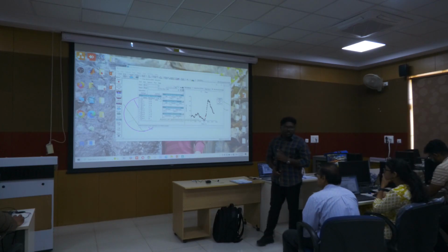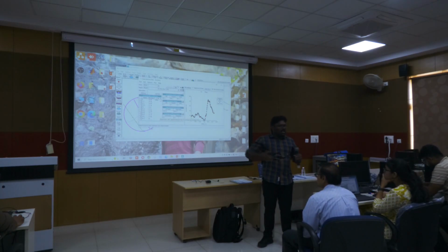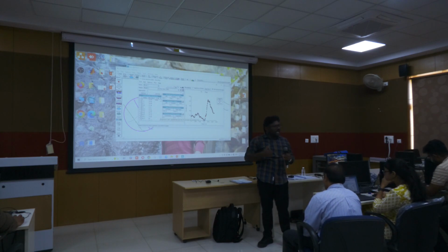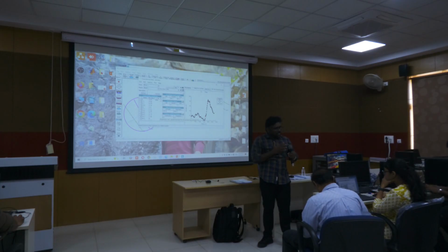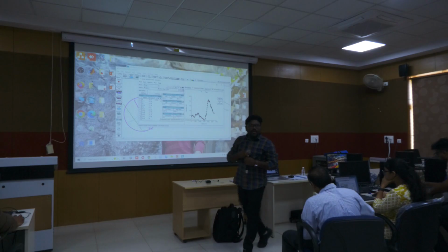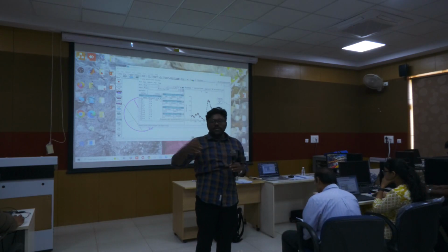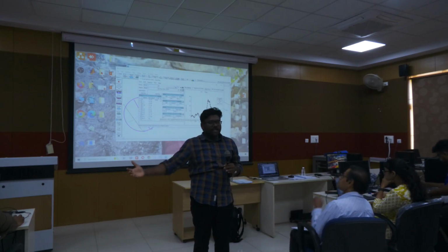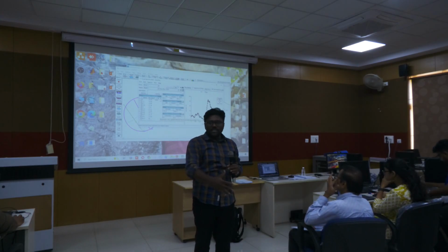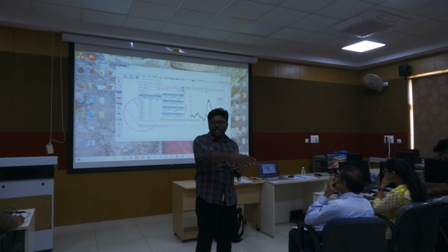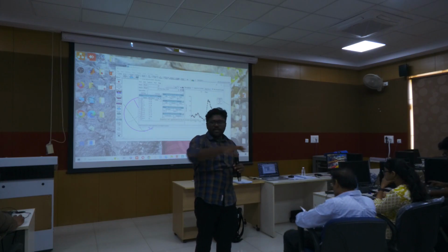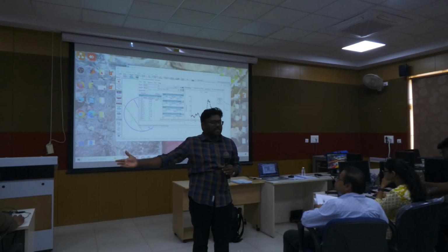Here, the next thing we do is, along the cross section, we don't have the roughness coefficient value. So we will assume the same roughness along the cross section. Okay. So usually what will happen? Compared to the flood plains, the roughness is low in the main channel, right? So the water will move freely. So roughness is more in the flood plains.